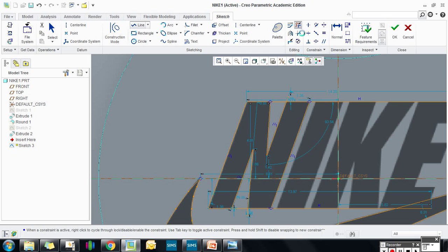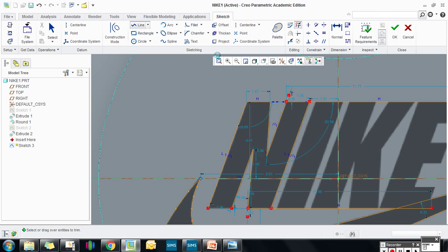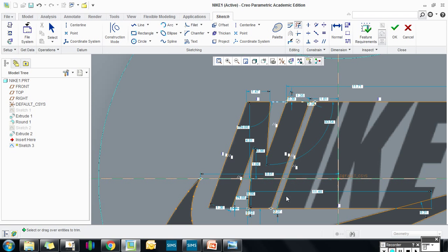While I'm here, I'm going to now just delete the line in between and the line in between that one at the moment, and then I'm going to carry on sketching. Go past. Again, get the delete segment tool, because there are bits here, there are connections, and it's important that we get rid of all of these connections.